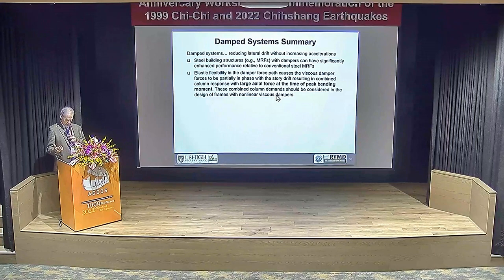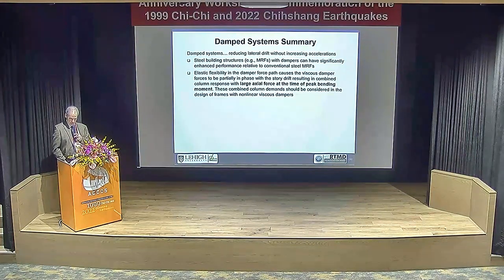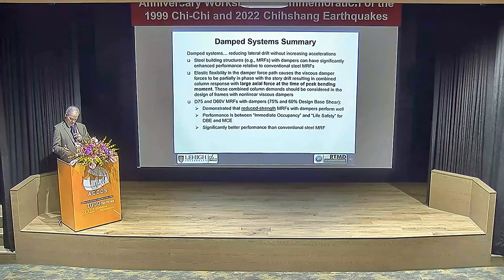So just in summary, you could control the drift without increasing accelerations. If you decide I'm going to control drift by just throwing a bunch of stiffness up there, you're going to raise the acceleration. So that's going to be important. And we showed, relative to conventional frames, even though I don't show it here, we got much better behavior. But again, that force path, that elasticity needs to be accounted for. And with the reduced design, we demonstrated that it can perform well.